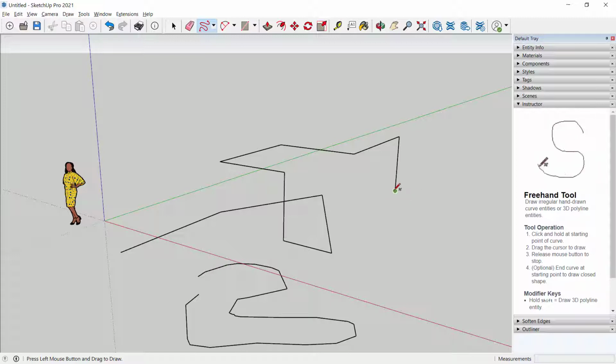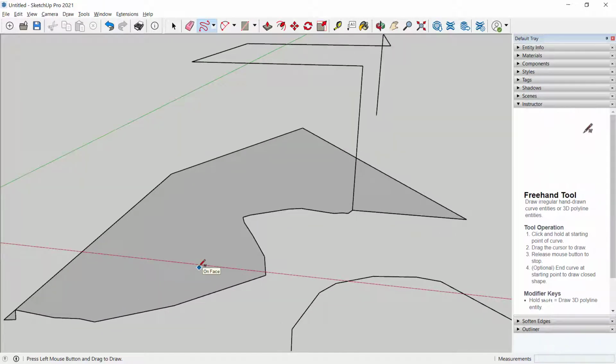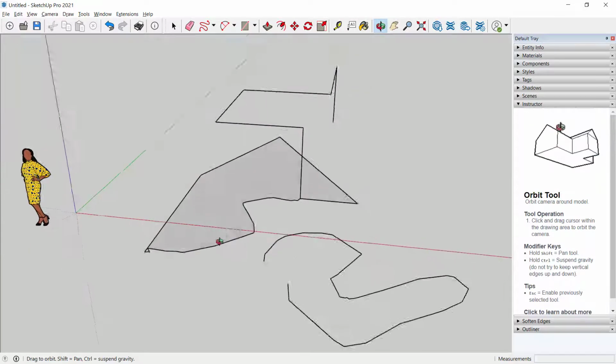You'll notice as before I've started drawing, if I move my mouse over an end point or a midpoint of an existing line, that SketchUp's smart cursor will recognize that point and it will give you that highlight. There's all sorts of great ways that you can create geometry, and this is one that's fun. I'm going to connect these 2 lines by going from endpoint to endpoint. And this shows you another cool feature of SketchUp, which is it can draw solid faces. Now, I don't mean solid as in you can eat off of them like a piece of cheese, but they are, in fact, filled in.